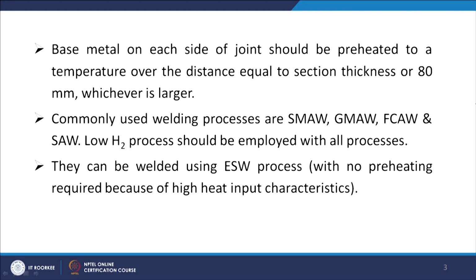Now, they can be welded using the ESW process, that is electroslag welding. In that case we do not require preheating because of the high heat input characteristic of the ESW process. So, in that way you will certainly have some difference as compared to the mild steel for these processes.